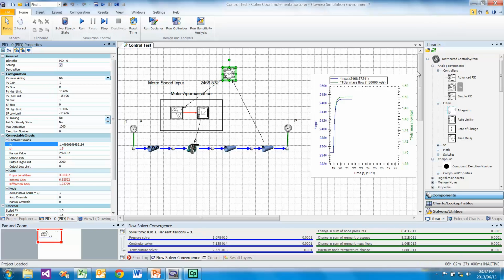In short, this is a simple tutorial to show you how PID controller parameters can be determined. Flownex can be used to easily determine step responses of a system, and the reporting capability can be used to log these responses so that the key parameters can be calculated. And using these key parameters, the P, I, and D constants for your controller are calculated.